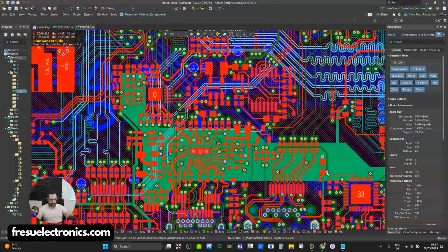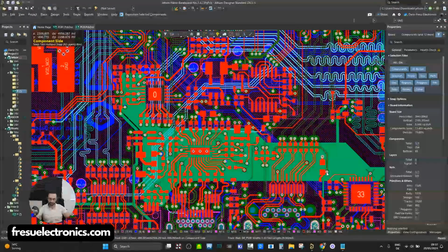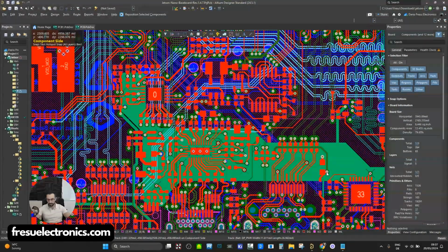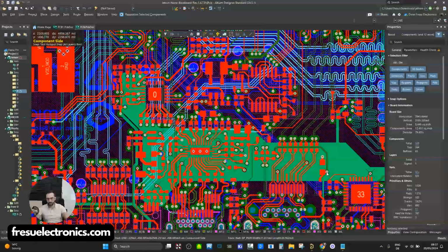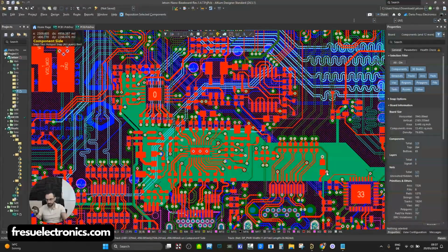And this is important, like in any other system, we need first to specify the requirements and then we need to start building it. So the first requirement is to provide a constant uninterrupted DC voltage source to the load. So we want the system to maintain constant supply during the operation. This is important because of course you don't want your processor or your microcontroller being interrupted during the operation. So we need to provide a constant voltage source to the load, which in our case is most of the time the ICs.